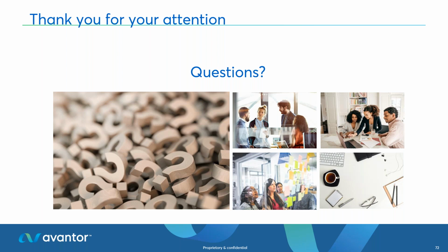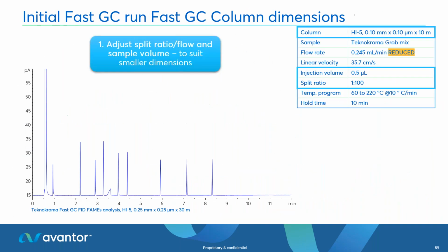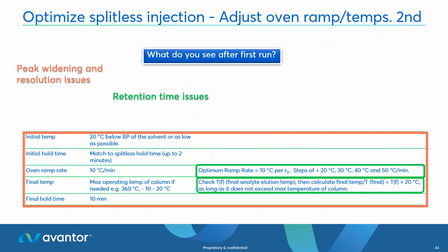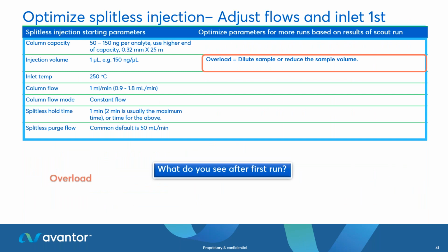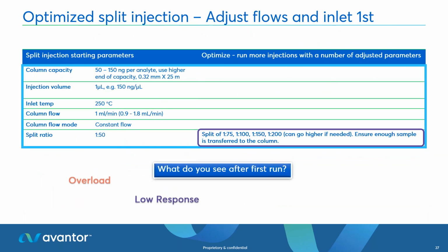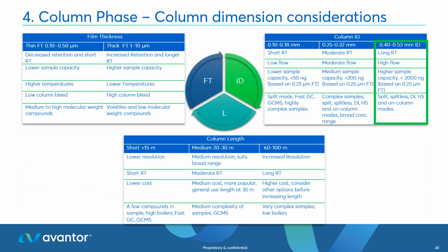It would depend as well if the peak broadening is occurring on all of the analytes, or is it a select few, or just one? And I think what you can have a look at, when we go back to harnessing the temperature, is adjusting the temperature and making sure that the analyte isn't staying on the column for too long. I know it is tough sometimes, especially if some of the methods are established and you don't want to change them too much.